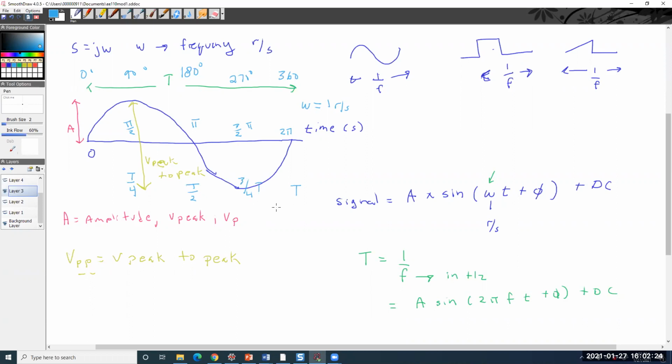And what happens when you're dealing with impedance and the frequency is a kilohertz? Well, you convert that to radians. But once that frequency is assumed and you calculate your impedance, you don't necessarily care that the period is a millisecond. You want to know where you are on the shape of this curve. Am I at pi divided by 2? Am I at pi? Am I at a quarter period, half period, 3/4 period?